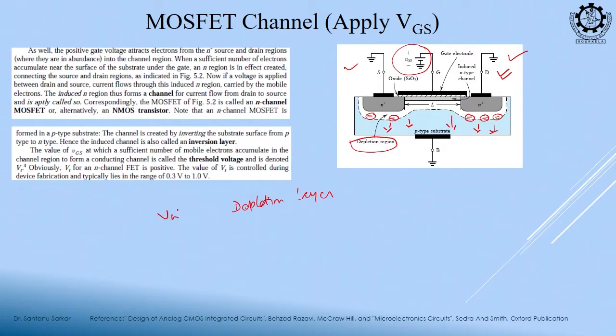Your Vg just started from 0, then your Vg is just greater than Vth. What will happen? Channel inversion, or a layer of electrons. Then suppose your Vg is higher than Vth as well as Vd is higher than 0, then what will happen? Current will flow.